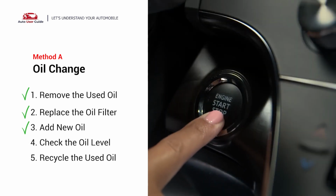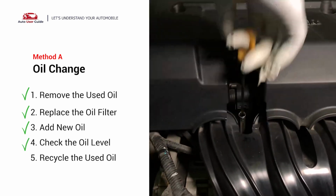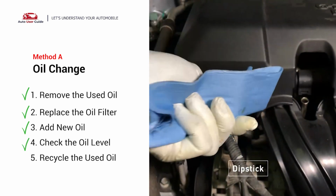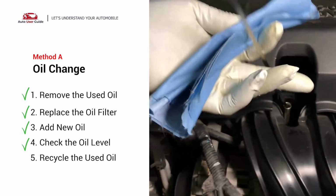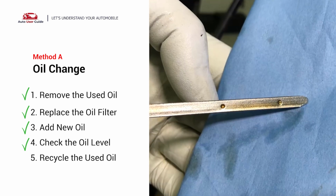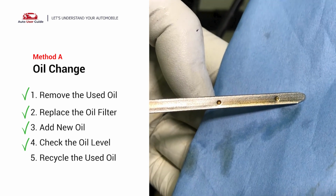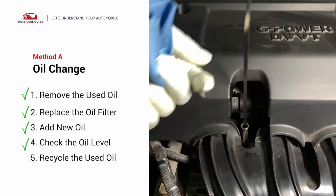After the oil change, start the engine and let it run for a minute to bring your oil pressure up, and recheck your oil level. To check oil levels, pull the dipstick out and clean it off. Replace the dipstick and pull it out again. The oil should be near the top dot or fill line. If it is close to the lower dot, you'll need to add more oil.